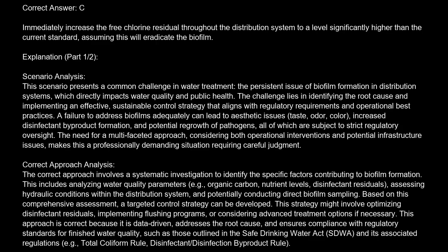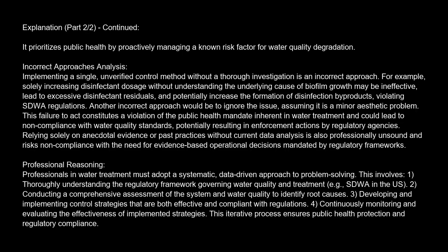This approach is correct because it is data-driven, addresses the root cause, and ensures compliance with regulatory standards for finished water quality, such as those outlined in the Safe Drinking Water Act, SDWA, and its associated regulations, e.g., Total Coliform Rule, Disinfectant/Disinfection Byproduct Rule. It prioritizes public health by proactively managing a known risk factor for water quality degradation.